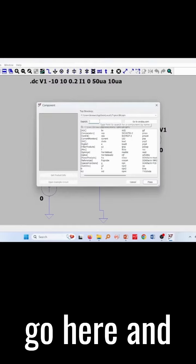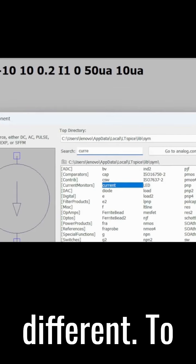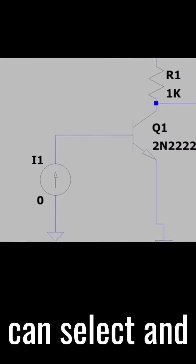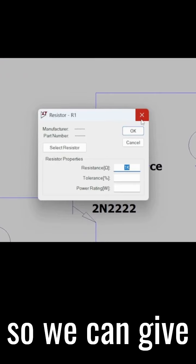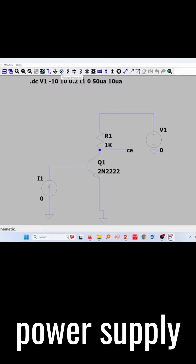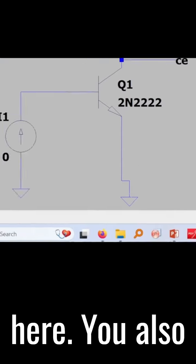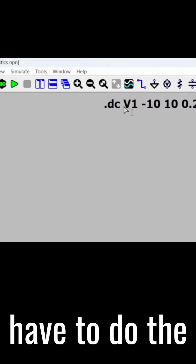So you can go here and select such a current source here, so that you can select and get the current source. Then you have to give the resistor. I choose this 1K, so we can give a value of 1K here, and you need a power supply also. Okay, this is a normal power supply that you can choose from here, and you can put it here. Okay, you also need to put the proper ground for this one, and so the main thing is you have to do the simulation here.